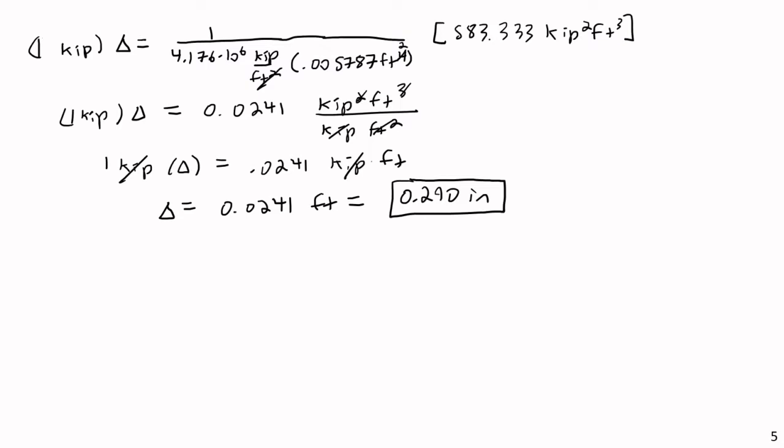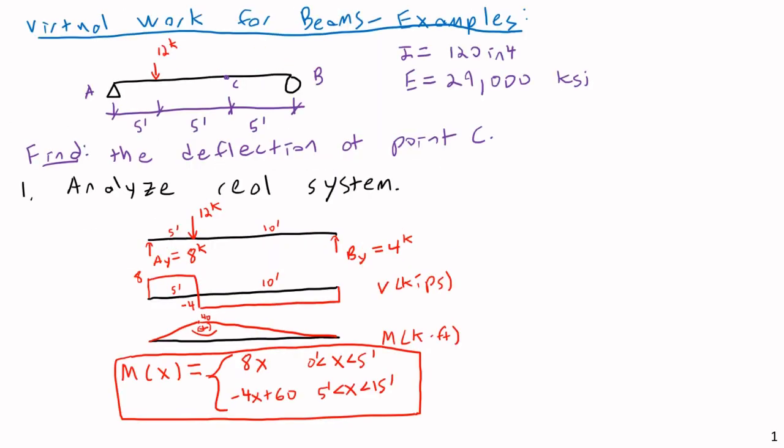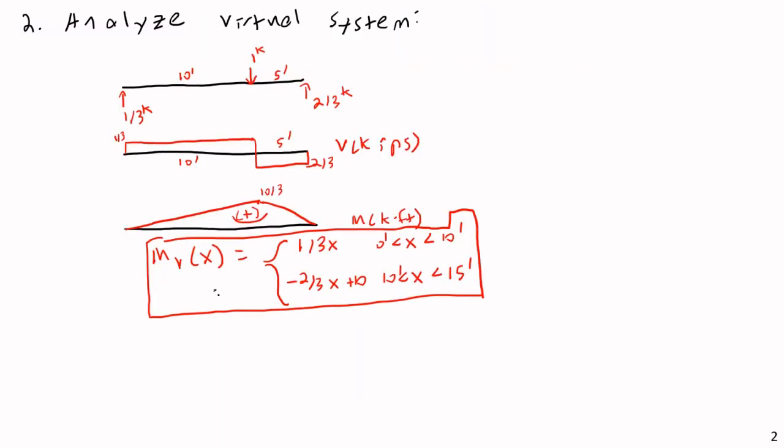So, working through this, we can see our general method. First, we set up our real system with the real loads, find the reactions, find the moments, and not just the moments, but the moment functions. Second, I go and apply a unit load at the point of interest.